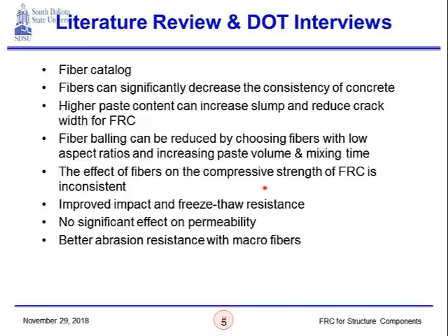The effect of fibers on the compressive strength of FRC is inconsistent. This is one of the interesting things that we found in the literature review. We found several studies, each showing different, basically completely contradictory conclusions. One showed that the compressive strength is increased by using fibers. Other studies showed it decreases. Other studies showed it does not affect the compressive strength.